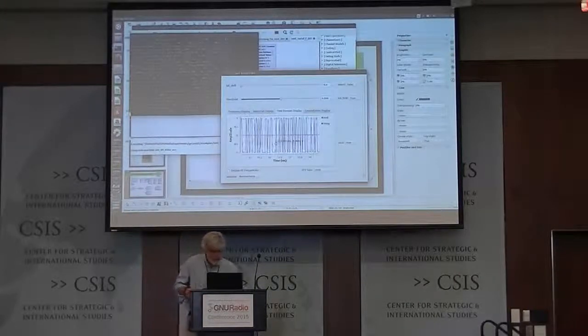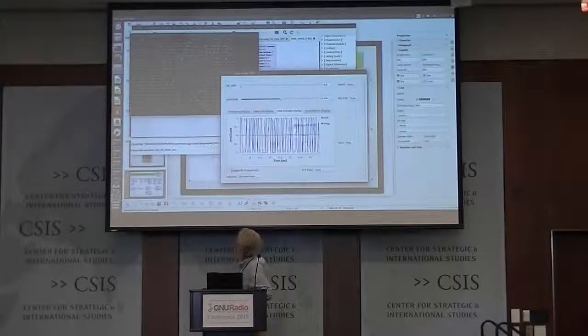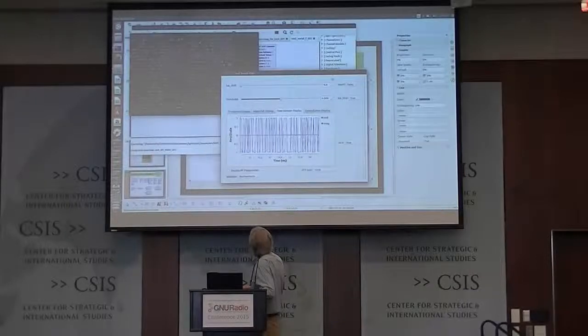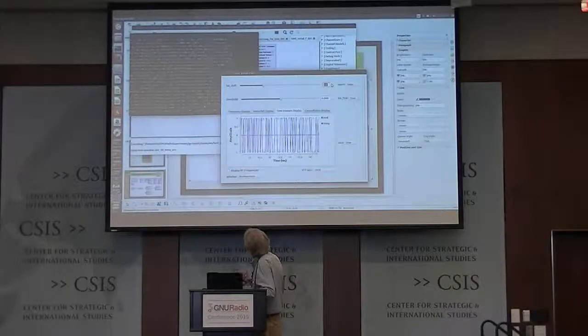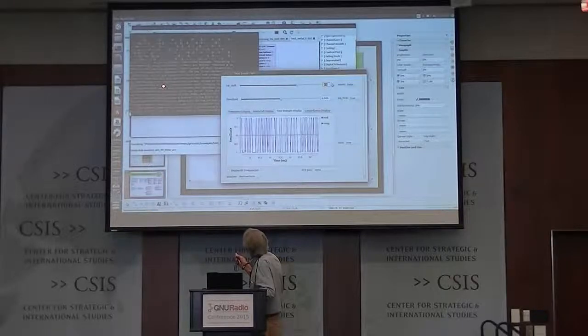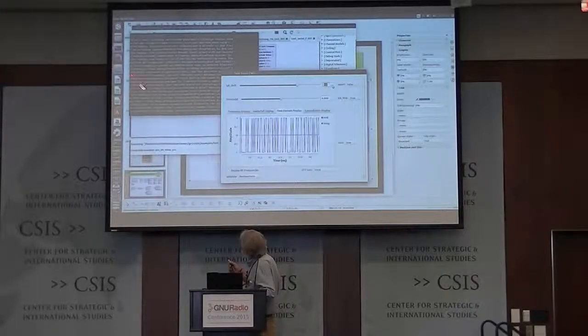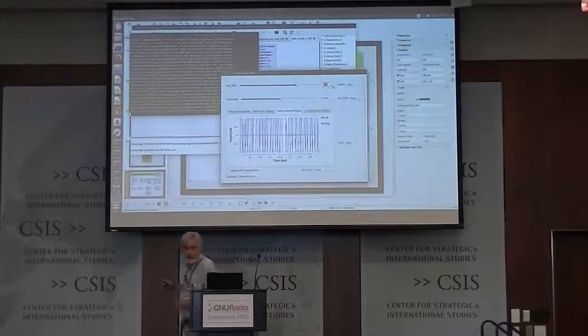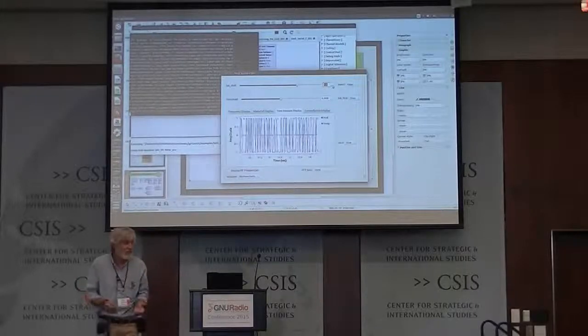So here's what I have here. I have to see how to control this. I can now change the bit shift because, of course, there's the question of how those things synchronize, or where the start is, the first bit of your ASCII code. So I can shift this over. You get to see over here how things change, and then magically, once you have the right setting, you get to see a message that's readable.